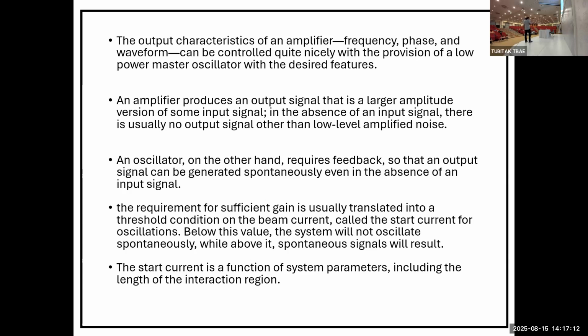The oscillator will start oscillating when you provide what we call feedback, right? You have to have a feedback. And for these devices, the feedback comes from the reflection from the edges. So at the edges, you're going to have some reflection happen, and this is what's going to cause the feedback and grow the signal.